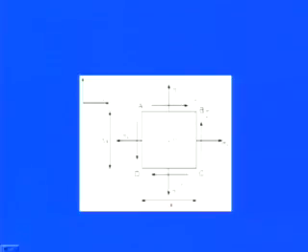So if we are discussing a simple plane problem where xy is there, how many stress components are there? In total we have 2 normal stress components and 2 shear stress components. So only 4 stress components are needed. No need to go for all 9 components.